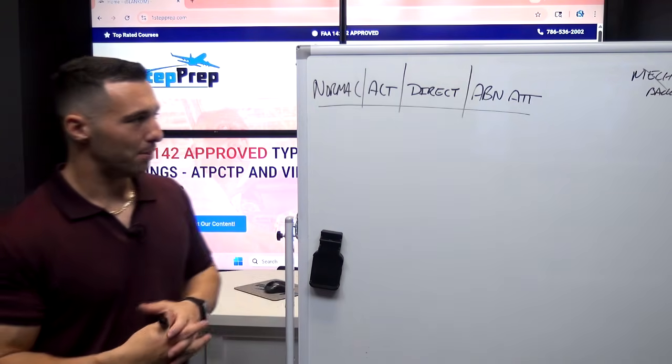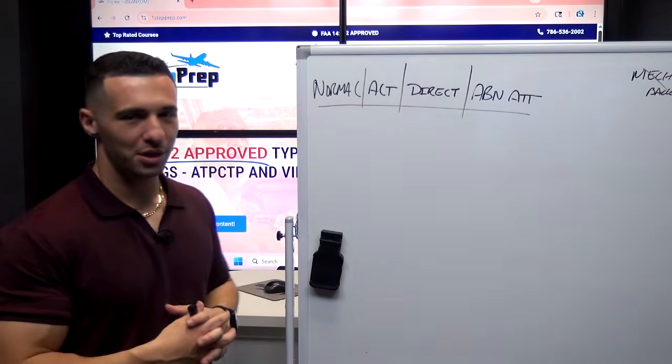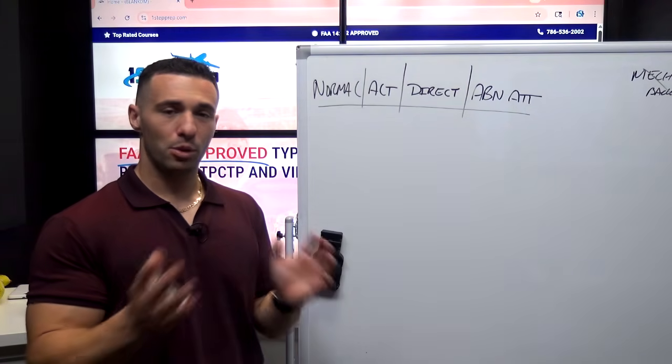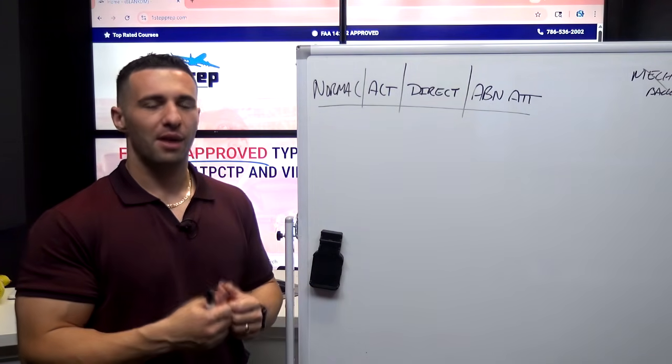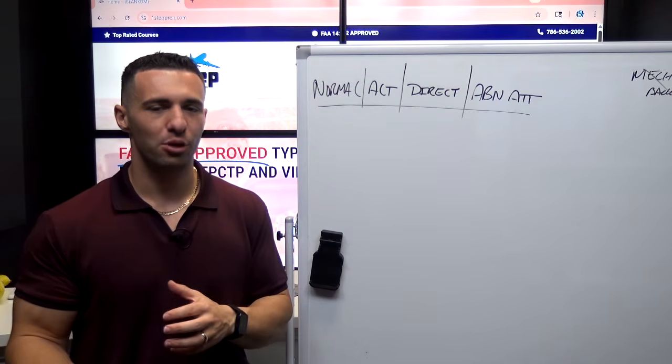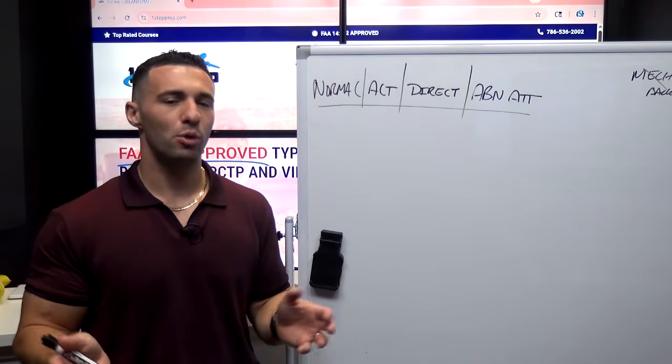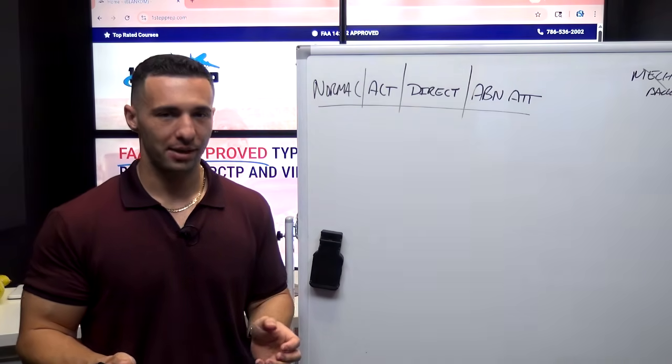So with that being said, I'm going to err on the side of the most recent revision I saw, which is basically that, hey, in abnormal attitude law, I don't have any protections, and then once I recover, then I retain G-load protection, and I'm going to stay in abnormal attitude law for the remainder of the flight.